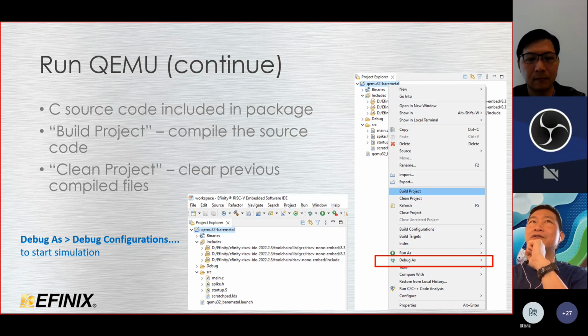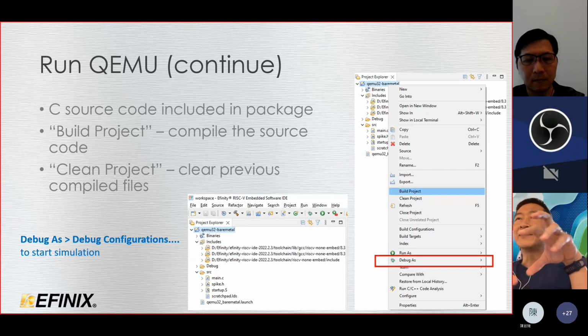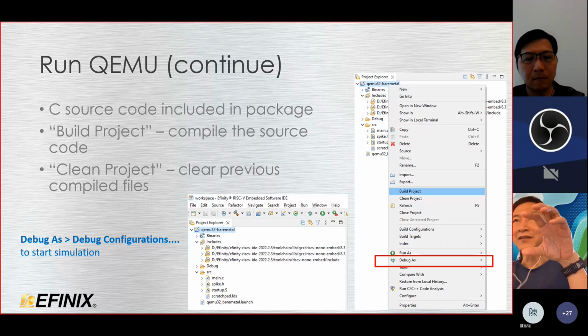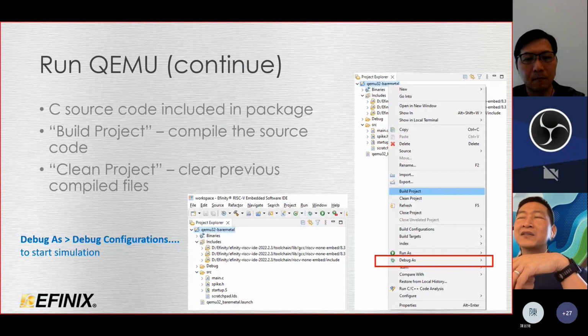Speaking of the design environment, I have a suggestion. Since you are integrating RISC-V in there, you will probably not only have the RISC-V, but also some coprocessor or accelerator next to it, talking to each other. Maybe it's a good idea for future work to construct a kind of complete virtual platform, including the RISC-V and the accelerator part, where users can write some high-level models, like in C or C++, to just simulate the functions. And the tools can take the whole into account and quickly return feedback about the approximate resource usage, for example, whether it is too big to fit into the FPGA, or where the bottleneck is going to be.